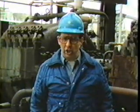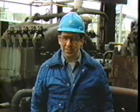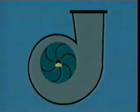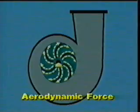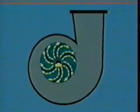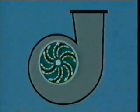Now let's take a closer look at compressor operation. When gas enters the compressor, several forces are acting on the moving gas. One of these forces is aerodynamic. An aerodynamic force is the same force that causes an airplane wing to lift as it moves through the air. This lifting force helps to move the gas from low pressure at the eye of the impeller to high pressure at the outer edge.